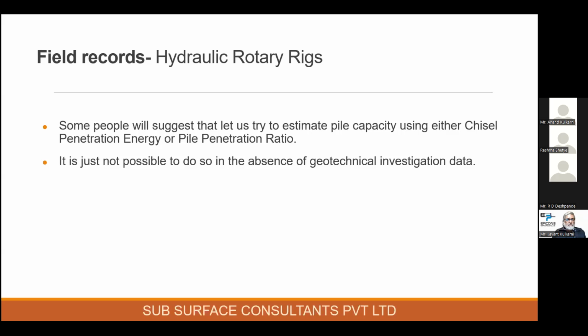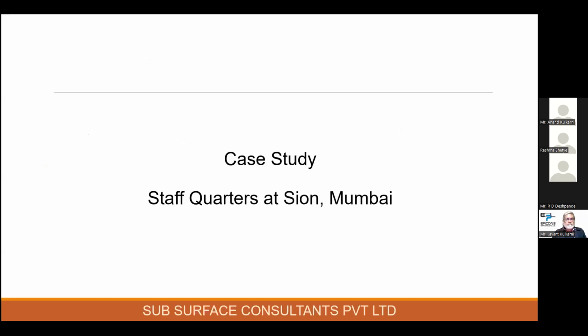Chisel penetration energy or pile penetration ratio are related to the geotechnical investigation data, like core recovery, RQD, and crushing strength. When you connect these aspects together with the energy levels, only then can you come up with the proper answer. But otherwise, to estimate the pile capacity in the absence of geotechnical investigation data is very hazardous. That is a caution, or an alarm, let's say, that I'm putting up here.